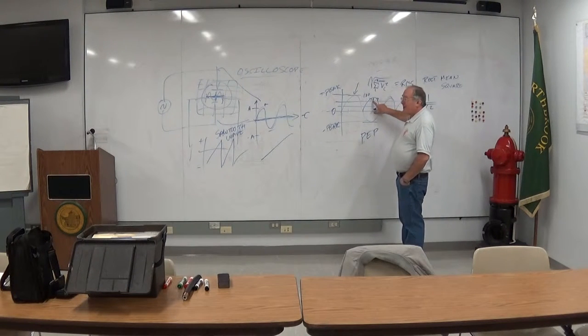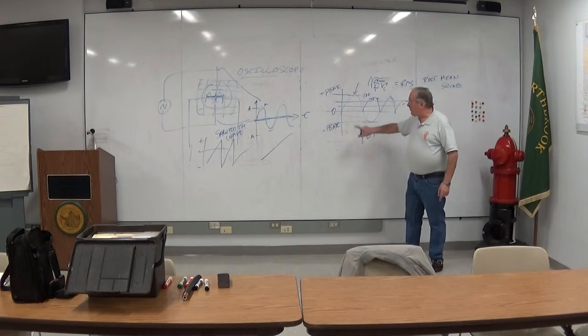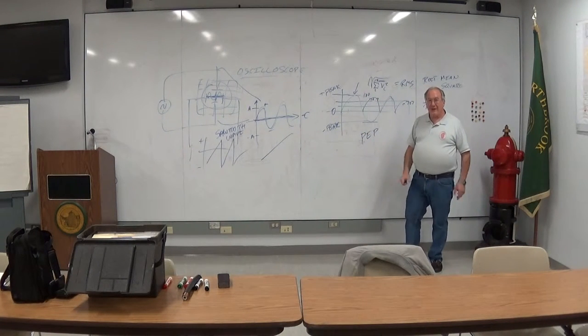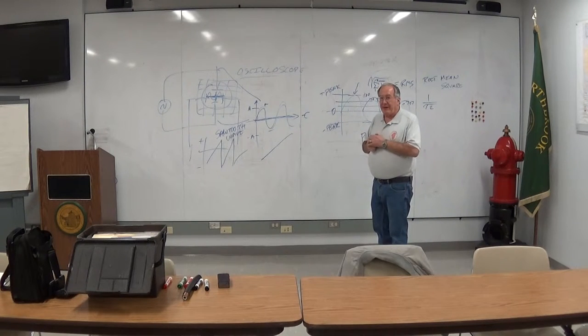If the value is 70.7 volts RMS, what is the peak to peak value? Well, it's going to be 200 from here to here. It's going to be 100 from 0 to here. Just a little pointer. All right, that's measurements for the most part.